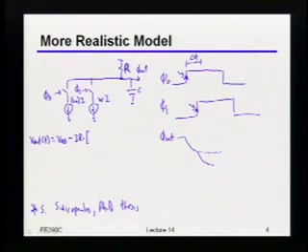What would be the equation of the impact of that on the output? 1 minus W times 1 minus e to the minus t over RC. Okay? And now, just to be sure that it's clear, because in 1 second we're going to have to add something else in, that's times a step.